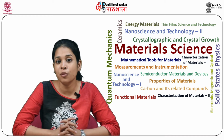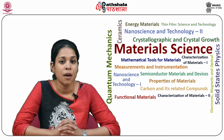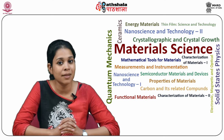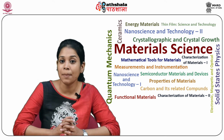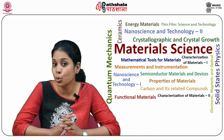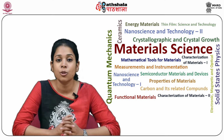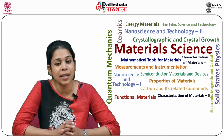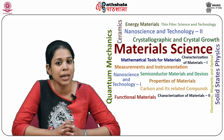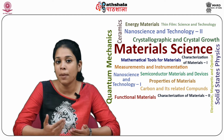So before moving further, let us discuss what ferrites are. A ferrite is a type of ceramic compound composed of iron(III) oxide, mostly combined chemically with one or more additional metallic elements. They are both electrically non-conductive and ferrimagnetic, meaning they can be magnetized or attracted to a magnet.